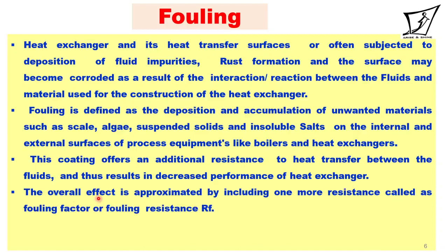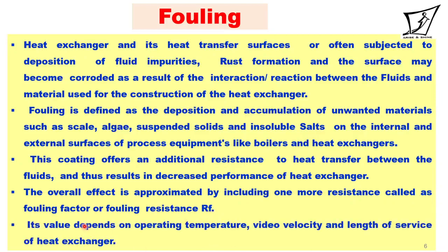The overall effect of this scaling and fouling phenomena is approximated by including one more resistance, apart from what we have discussed in the previous slide, called the fouling factor or fouling resistance, and it is generally represented by capital R suffix small f, Rf. The value of this Rf depends on the operating temperature of the fluids, velocity, that is moving velocity, and length of service of the heat exchanger.